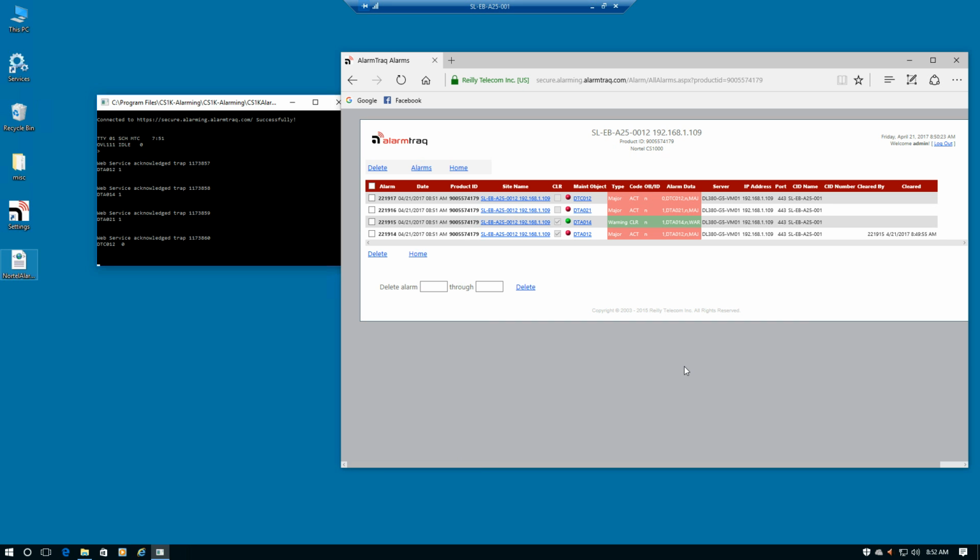We should be able to see those alarms now if we were to open up my internet browser so I can take a look at these alarms. I'm looking at the secure alarming on the far end of the circuit at our NOC, and as you can see, we just received the DTA 12, a DTA 14, a DTA 21, and another DTA 12. That one's on loop 0.